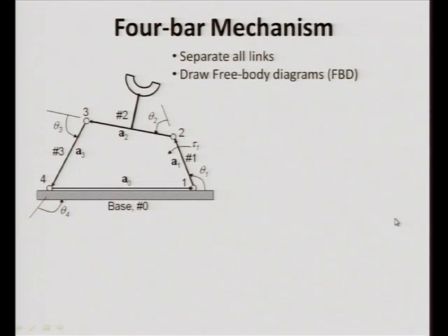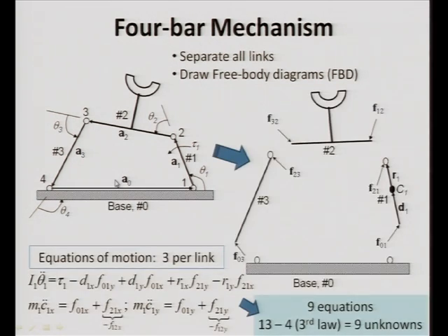Okay. Now, before we go to the parallel manipulator which has many closed loops, let us talk about one closed loop, where we have solved the kinematics, that means I have solved theta 2, theta 3, and similarly for given angular rates for the first joint I have also calculated theta 2 dot, theta 3 dot, and similarly the accelerations. So theta 1 double dot is a known quantity to me, and I 1, the inertia, I know for the given length and mass properties.